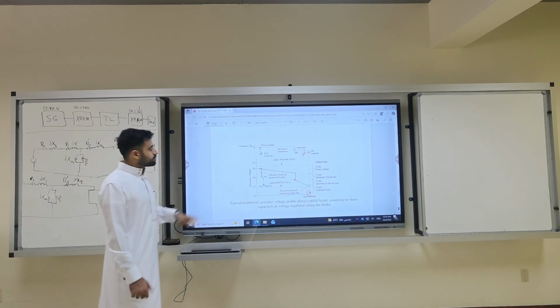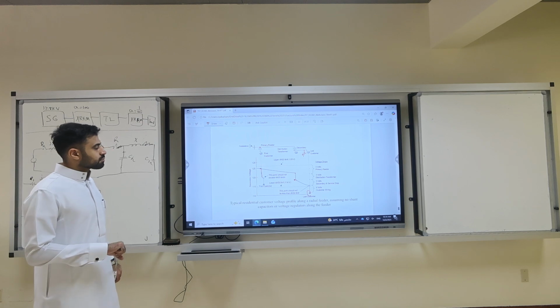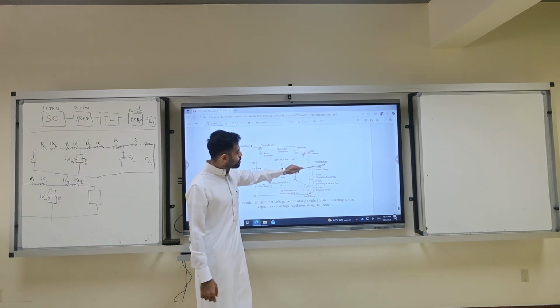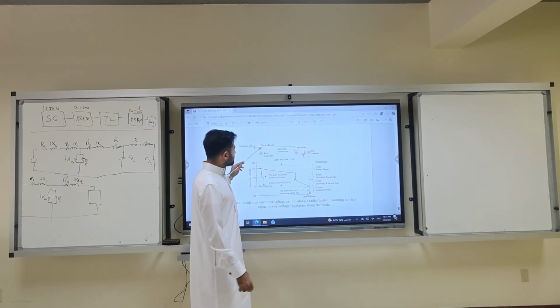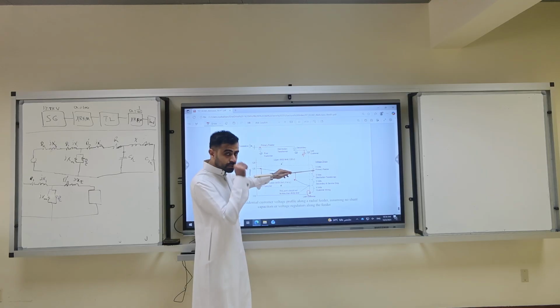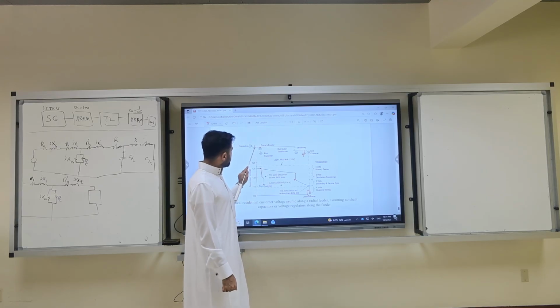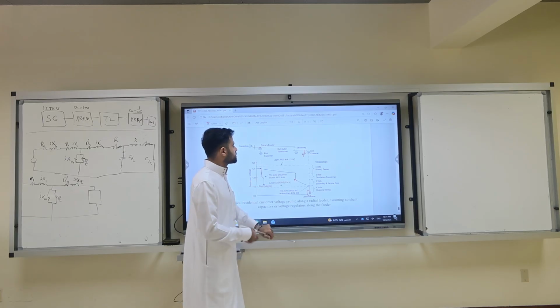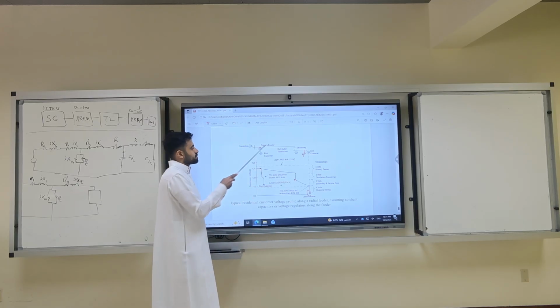What I'm telling you is count for voltage drops. 3 volts for the primary feeder. So the full length of the primary feeder will drop 3 volts. If you only go this area, you will drop this voltage. If you're in the middle house, it will be here. But also you add the distribution transformer, which are these.